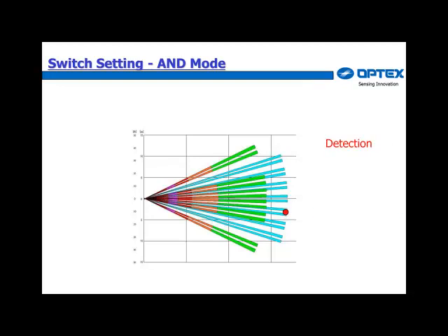So be very careful. The default position for this switch is OR mode, which is used for setup, but the OR mode is way too sensitive for practical use. So when you're finished with setup, remember to put that switch back into AND position. Very important.